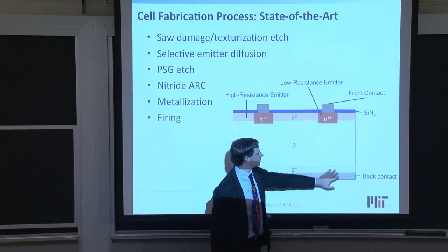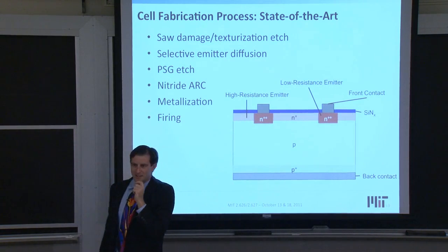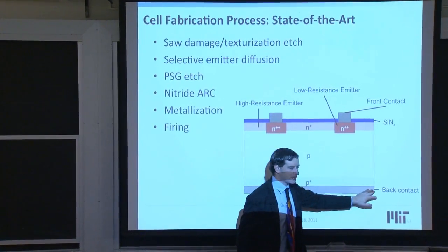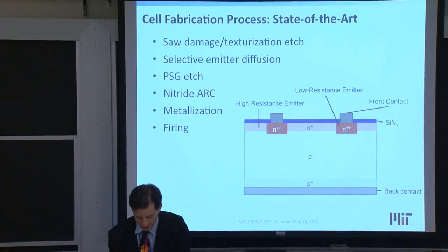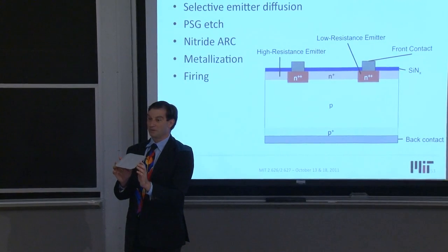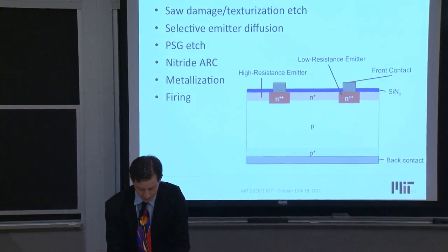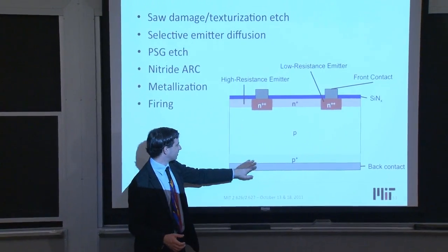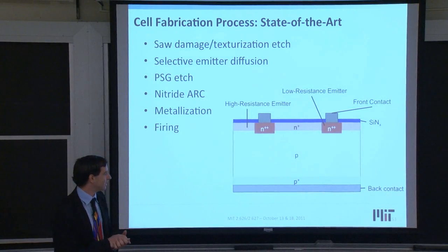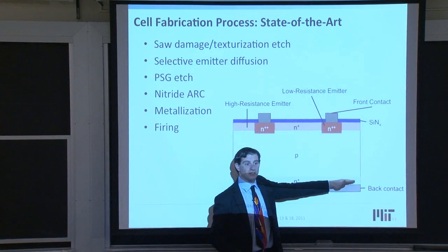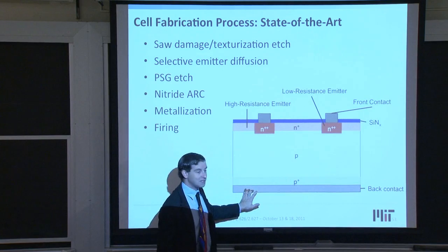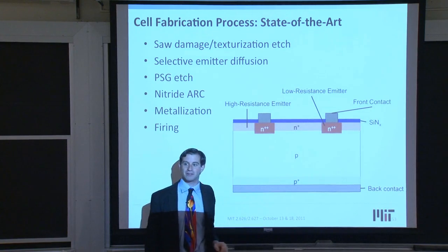And so for each of these different processing steps, somebody had to sit there and think deeply about optimization of different functions. The aluminum on the backside, somebody had to think about, gee, how do I prevent the wafer from bowing too much due to coefficient of thermal expansion mismatch between the aluminum and the silicon? Somebody had to think about, how do I create the right eutectic with the silicon? The aluminum silicon eutectic is at around 577 degrees Celsius, so that you create a good ohmic contact in the backside. How do I diffuse in a certain amount of the aluminum to create this back surface field to prevent back surface recombination? How do I get the right back surface reflectance of the light coming off of here so that I have multiple optical bounces through my device?